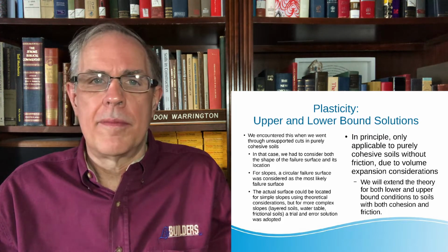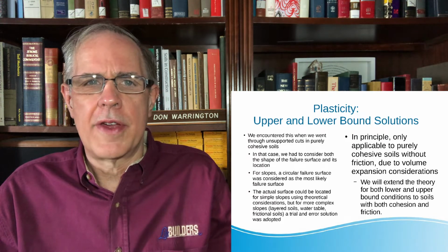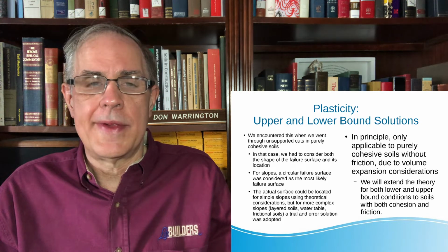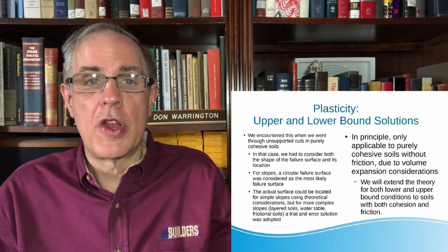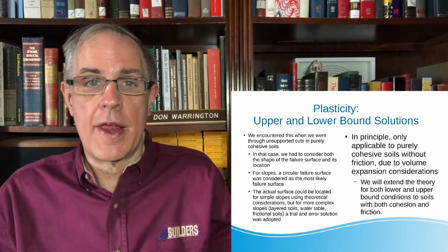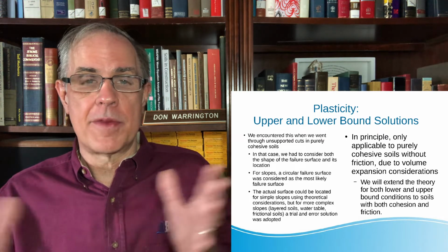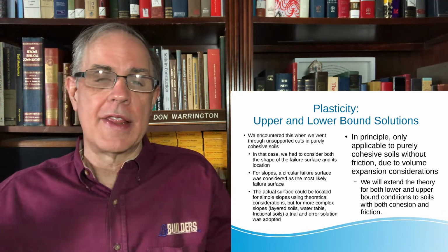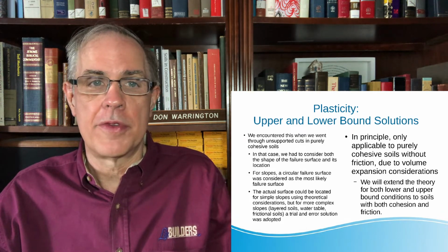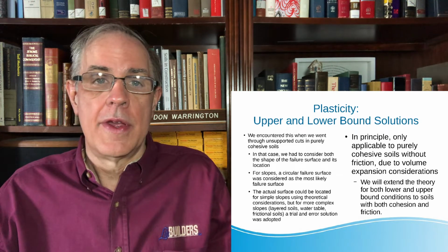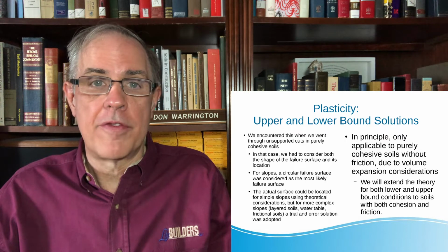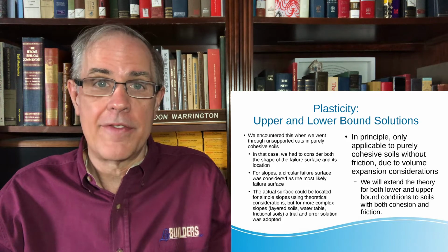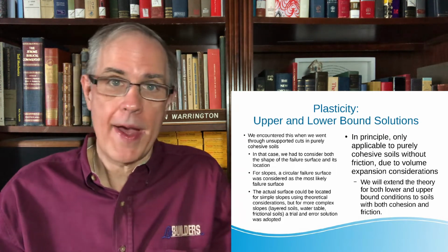Plasticity: basically the idea is if you start loading a foundation progressively, sooner or later you're going to induce, and basically we do, a failure surface. You've got a nice continuous medium where a surface or a line of plasticity forms. Obviously what we want to do is prevent that line from completely forming, but to do that we have to know how it gets there, if it actually did, and then work our way back.